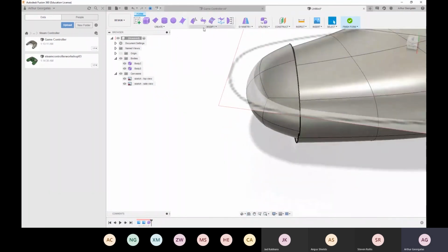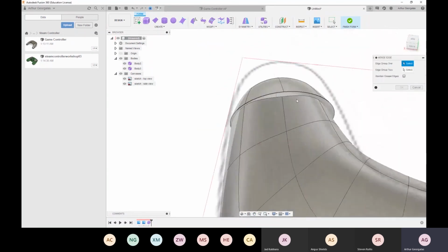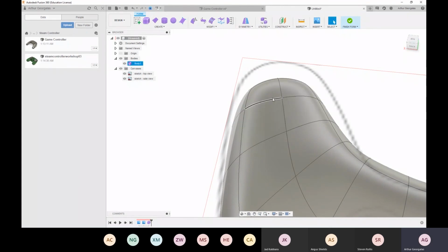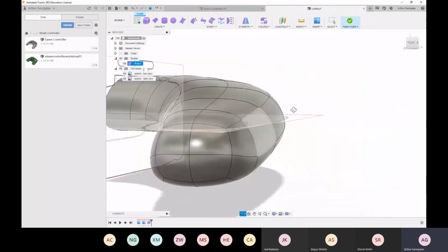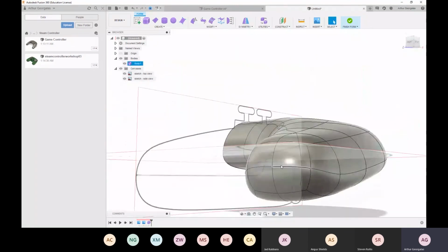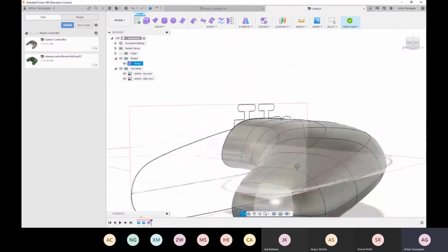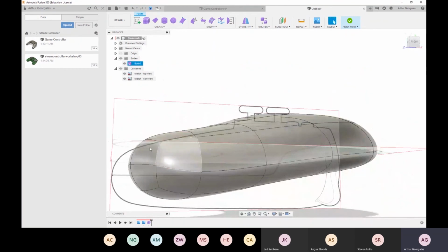Or what we can just do is go merge edge, which is a much easier way to do it. We double click this to select the loop. We select where it's going to group to, and we do that. We go OK, and it just does it. It merges all these ones to that one, depending on which one you select first. And right away now we've got this, which is sealed up really nicely in 4. That still gives us heaps of control over the surface, as opposed to the one that bridged weirdly across.